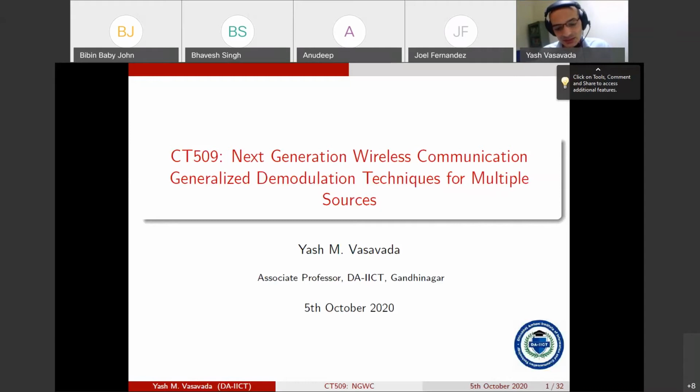There we had some nice, clean basis functions that were all orthonormal because the definition of basis function was up to us. At the transmitter, we had complete freedom in defining those basis functions, and so we said that the best way to define the basis functions is to make them a complete orthonormal basis set.